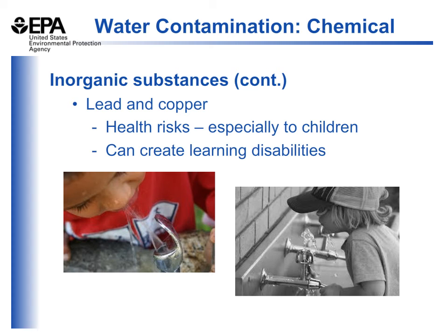If we can keep the pH at a neutral level at about 7, we will minimize the amount of lead or copper that will be leached out of the pipes. If the water is too acidic, it will actually remove copper and lead from the plumbing system within the home, and this can often be seen by the bluish-green tint that will collect along a sink or a bathtub if the copper is being leached out of the pipes.